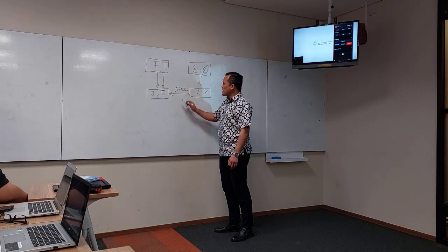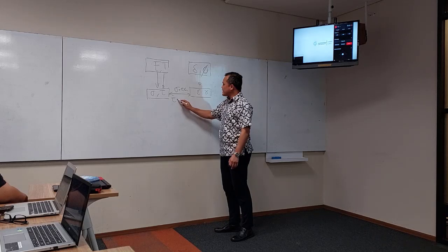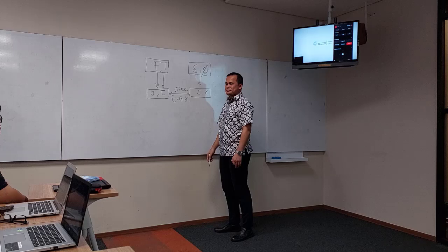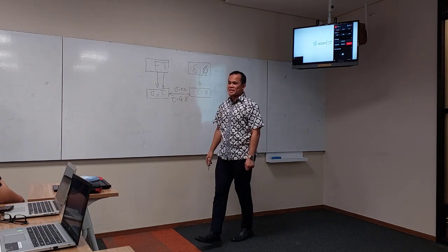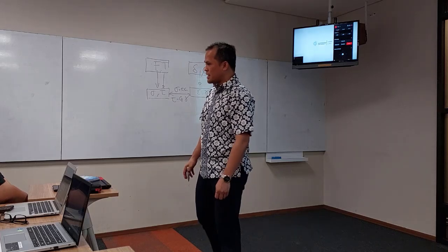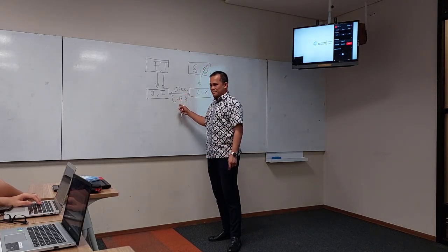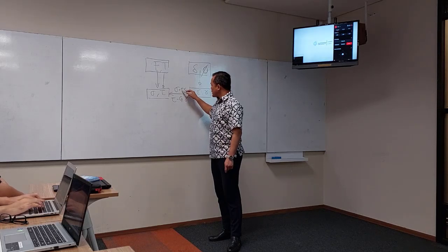Young's modulus. Can you use E? You don't think so? You are correct. So, we call this G. Remember? G is the shear elastic modulus. We no longer call it Young's modulus. It is elastic modulus. Elastic modulus under normal stress, elastic modulus under shear. So there is a relationship between E and G, by the way.